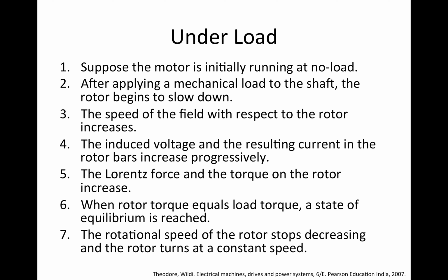The most important thing for us to remember is that at a state of equilibrium, motor torque equals load torque. Rotor speed is different from the synchronous speed. It's different from the speed of the magnetic field. The torque is the same, but the speed is different. And the relative speed, or the speed difference, is such that the induced voltage, current, and the Lorentz force produce the needed motor torque that balances the load torque. So that's probably the most important thing for us to understand.